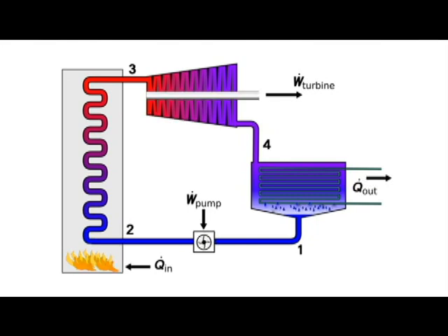The following is a typical Rankine cycle with a boiler, pump, turbine, and condenser. The efficiency is equal to the turbine work minus the pump work, divided by the heat input from the boiler. Now we are utilizing the waste heat from the condenser as an input for the thermoelectric. This is similar to the cogeneration cycle. The overall efficiency of a typical Rankine cycle is around 42%. Adding thermoelectrics will increase the overall efficiency.